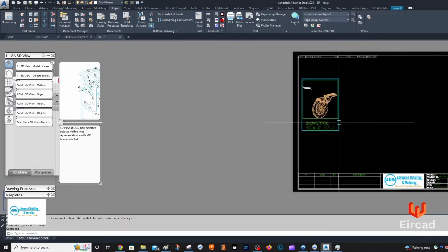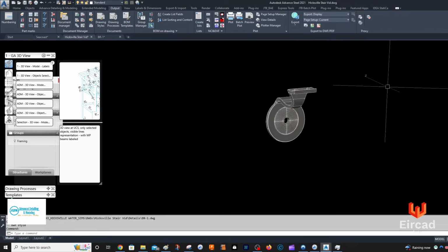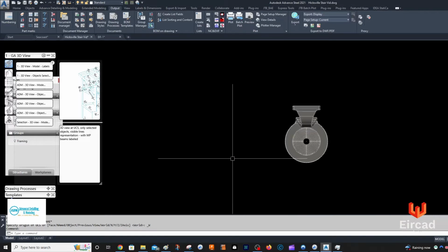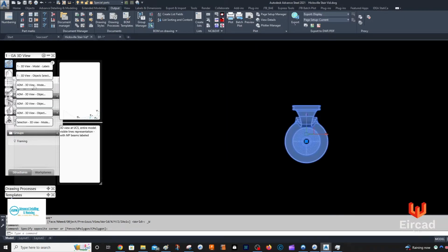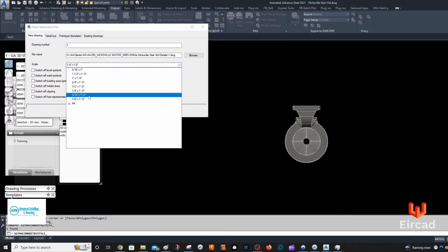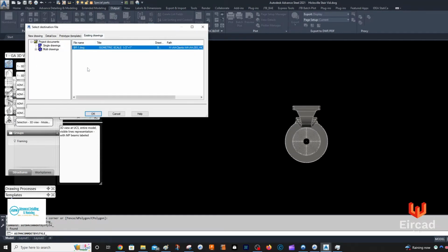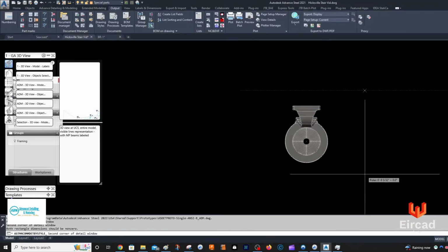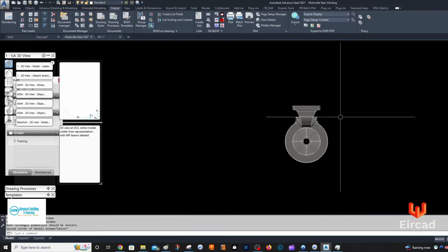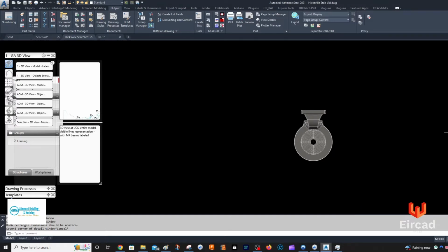So what I would then do sometimes is you're going to go in here, and then I would go back to the home view and come back in here and select it again and go to another 3D view and modify and try and get the scale right this time beforehand. And existing drawing, okay. Oh, I'm looking in the wrong way, so I need to fix my UCS because my X direction is up in the air.